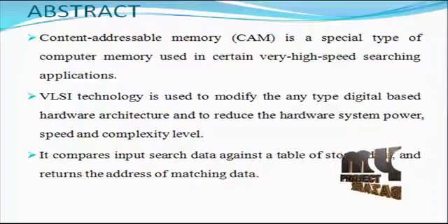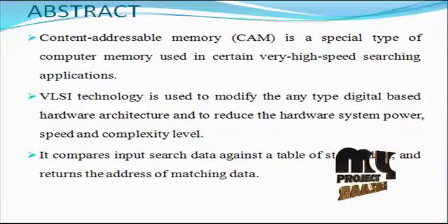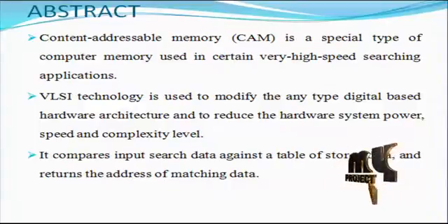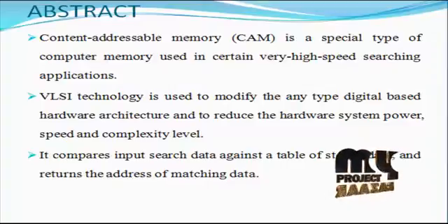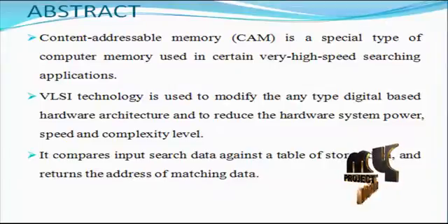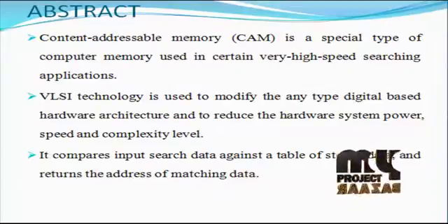Therefore, the dynamic energy consumption of the proposed design is significantly lowered compared with that of conventional low power CAM designs. Given an input tag, the proposed architecture computes a few possibilities for the location of the matched tag and performs the comparison of them to locate a single valid match.